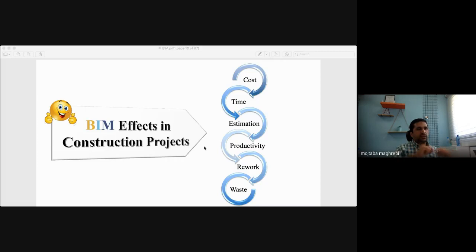Again, if you want to do it manually, you need to count them one by one. By BIM, with a few clicks, it gives you an updated number of the windows. You don't need to start counting. You just press it. Okay, what is the number of windows that I have? It was, for example, 100. Now I will delete some windows and then just update it. Just press update. You can see that 100 drops to 80. Easy. That is how you could monitor the projects for productivity.